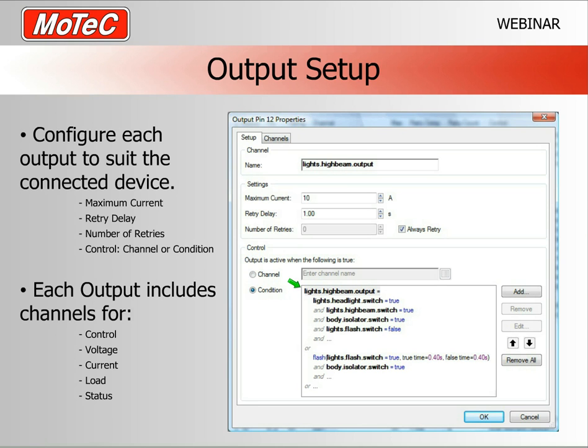The current is the instantaneous current going through the device, and the load is, as I described earlier, like a rolling average of the overall load on that output. And this is the way we allow, for example, surge currents and other short-term intermittent currents to not just trip the system out. So both of those parameters are interesting and useful, and again, they can both be logged.